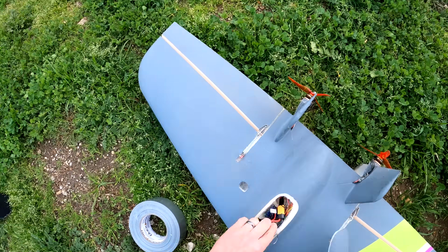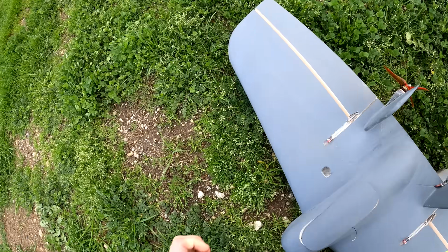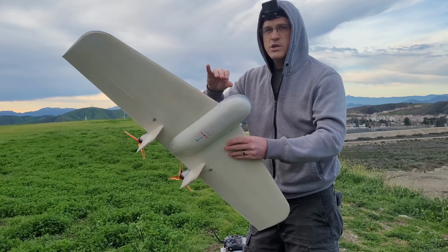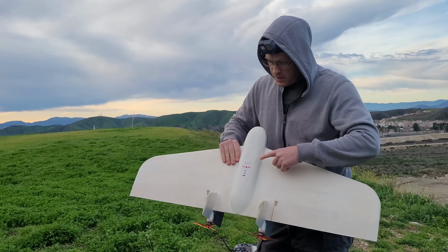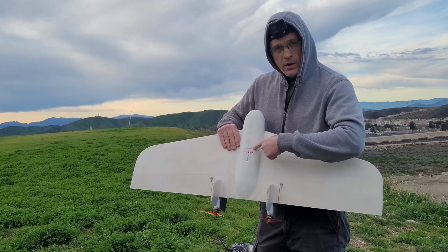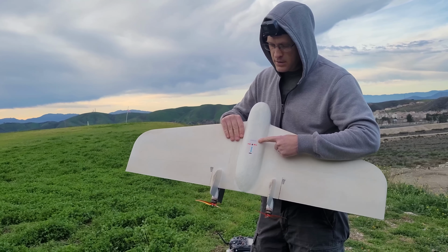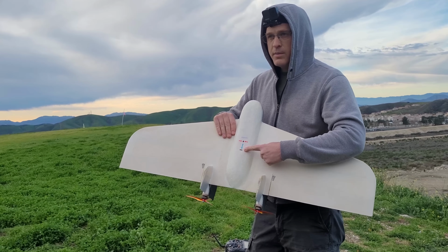With the aircraft center of gravity further to the rear and prepped to get wrecked, it was back to the field. So here's the neutral point in red, around which all the aerodynamic forces are balanced. Last time we had the center of gravity up here in front of the neutral point, and that's normal, that's a stable configuration. Now we've moved it all the way back here.